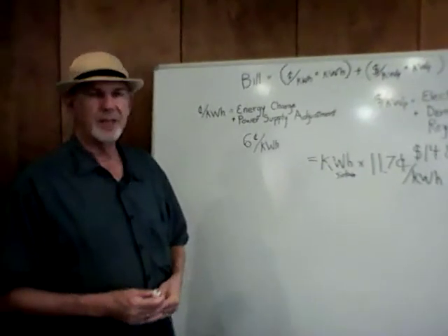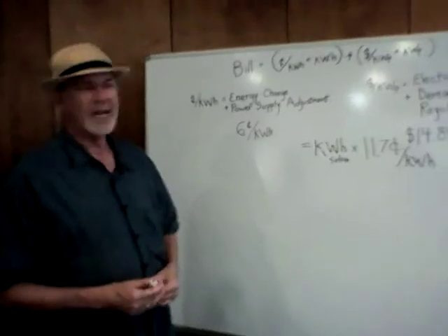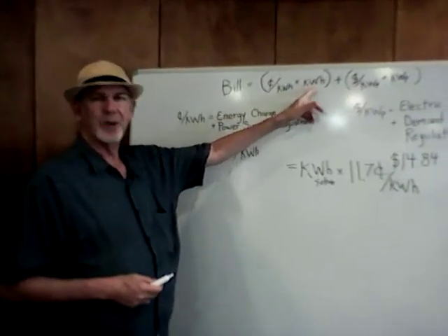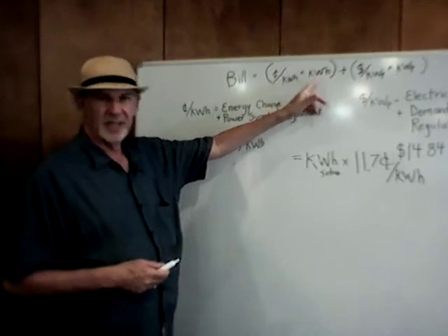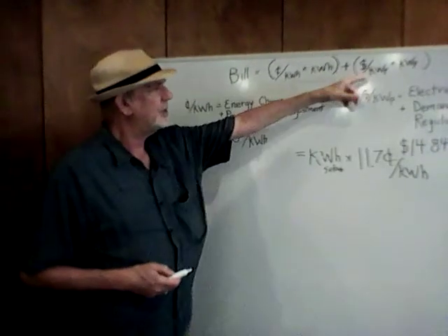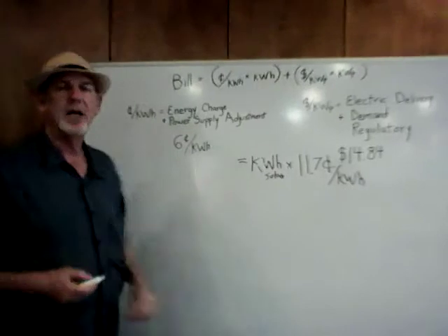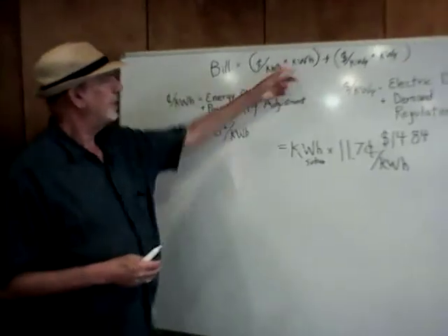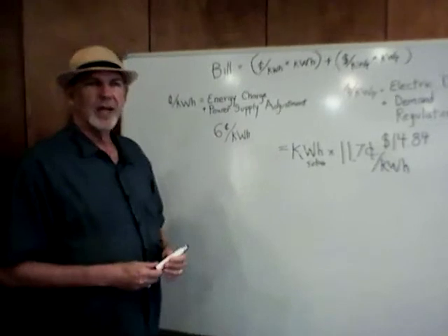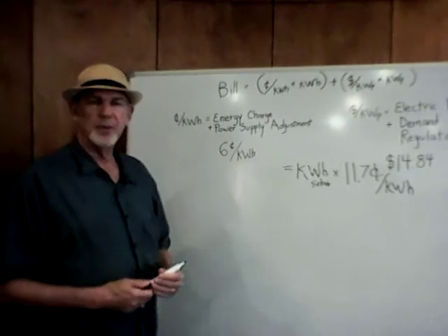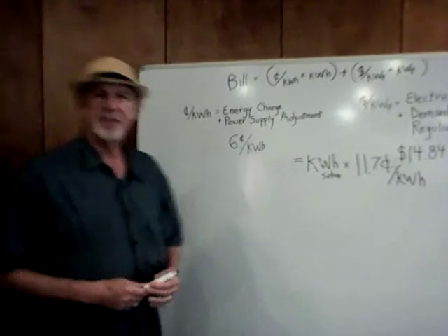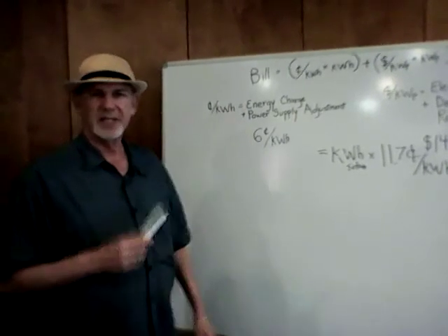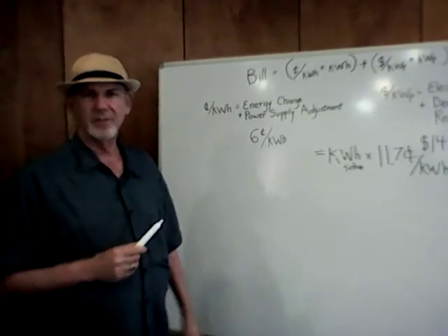They reduce the kilowatt peak. They actually don't do much at all to change the kilowatt hours. If anything, they will increase it slightly, but the savings due to reducing the kilowatt peak greatly exceed the additional cost that you incur through charging the battery. And when we show the graph of a typical electric usage profile, then we'll show you exactly how batteries work in a building.